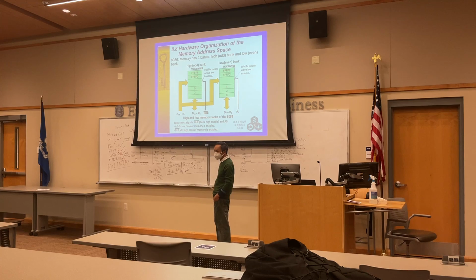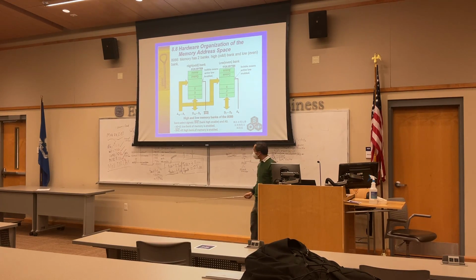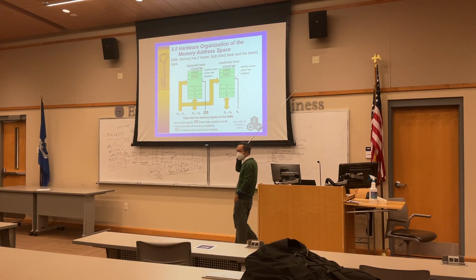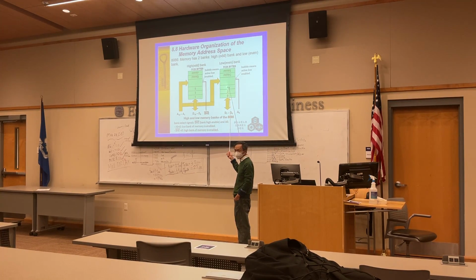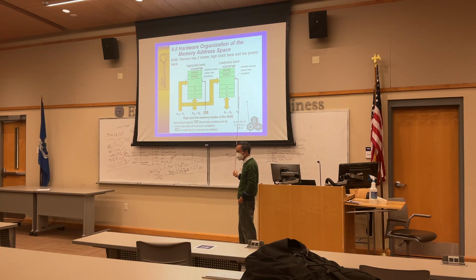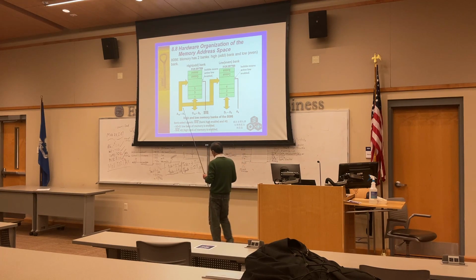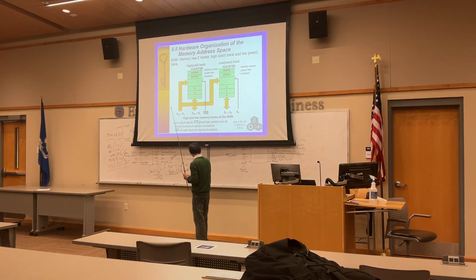Okay? Now, if my data is in the lower bank, that means it has an even address. For an even address, is address bit A0 1 or 0?